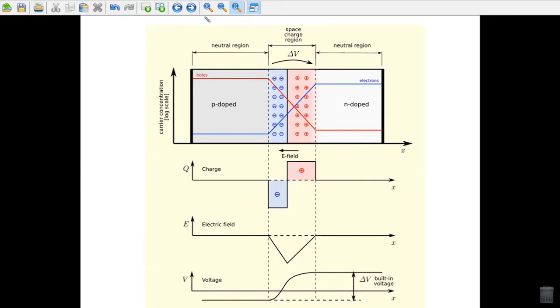Depending on how the distribution is changed, a semiconductor is doped to become either a p-type or n-type semiconductor. If the band structure is such that free electrons are more easily generated, it becomes an n-type semiconductor. If the structure is such that electron holes are generated, it becomes a p-type semiconductor. In this case, an electron hole refers to a place where an electron could exist but doesn't. Such a hole still conducts current.